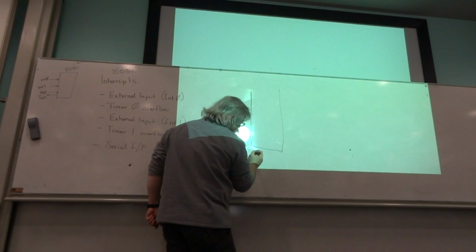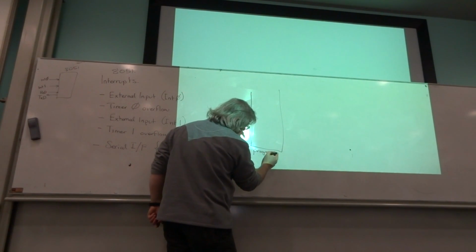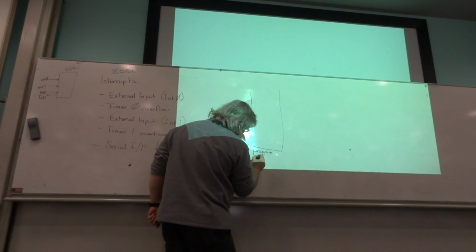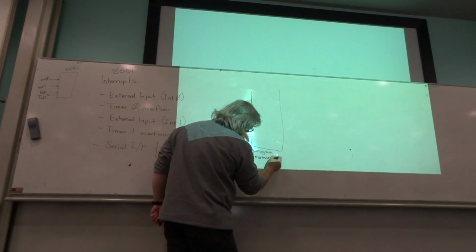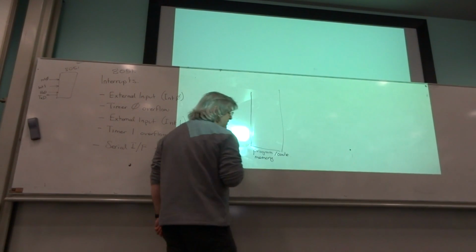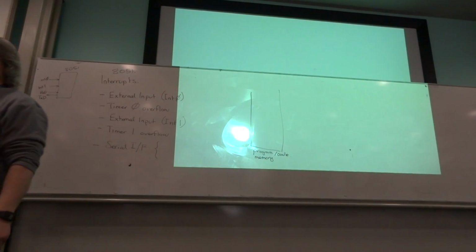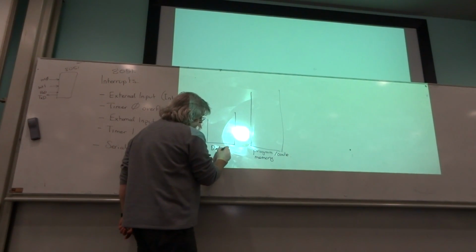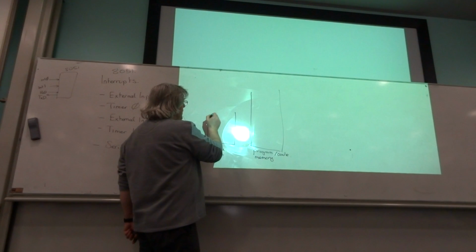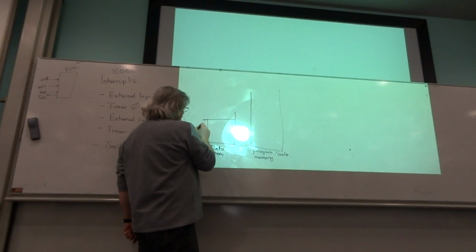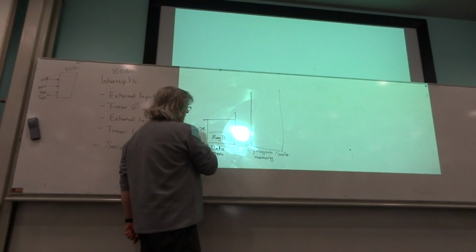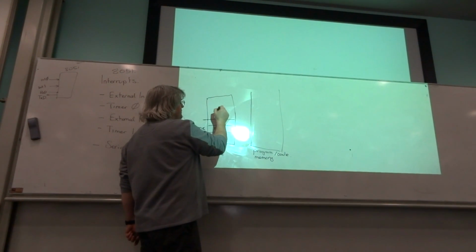Inside the 8051, you know there's a type of memory called program memory, code memory. There is also data memory. Okay, we've got data memory over here. The data memory is that, if you like, 128 bytes of things that include things like the register banks, bit addressable, general purpose, and then above that, we've got the special function registers.